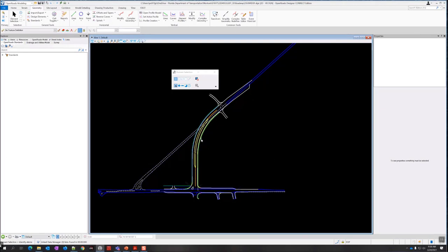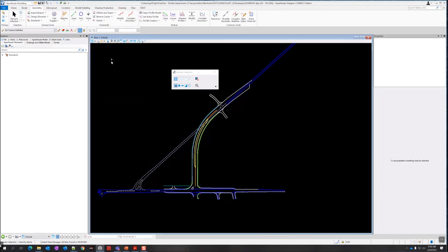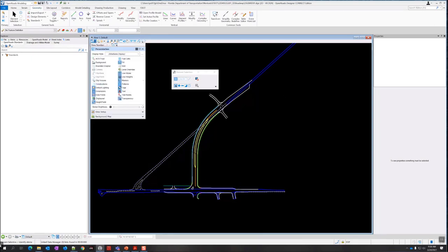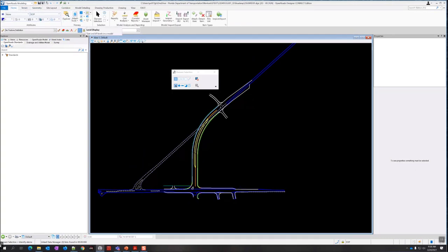All right, so I've got my plan view open. And in the view attributes, we just want to make sure constructions are turned off. So uncheck that. You can use F7 if you want, but this way I can see the status say, hey, it's off. We need to turn off any reference files, and they may already be turned off, but let me just go check. So I'm going to open the level display manager, because I've got to turn off some levels too. So I went over to the Home tab on the primary level display.